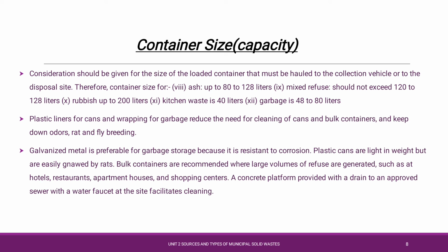And also a concrete platform is provided to drain off the waste water or sewage. If the organic waste contains water, the moisture can be disposed of through a proper outlet opening at the end of the container, through the proper sewerage system within the concrete platform, which is provided beneath the container's placement.